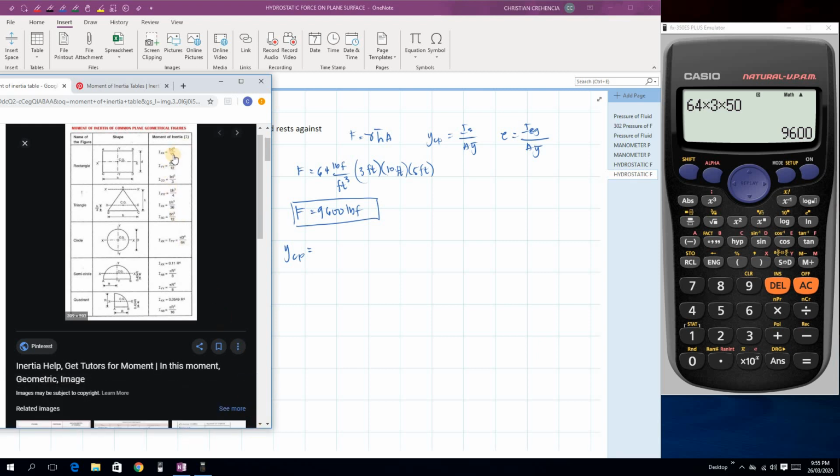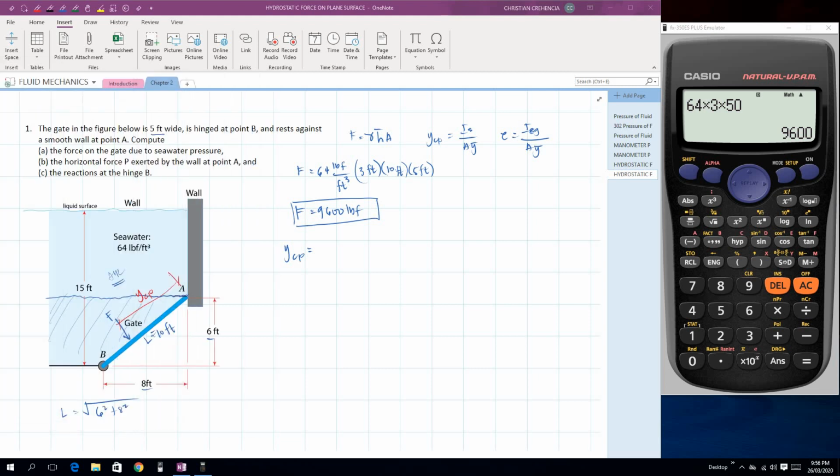Okay, so from the centroid, about x-axis, so yung B is yung width, okay. Then yung D is yung depth. So about x-axis, so that is yung width times depth cube, BD cube over 12. Pero if about sa base nito, rectangle natin, about CD, then this is BD cube pa rin, pero over 3. Okay.